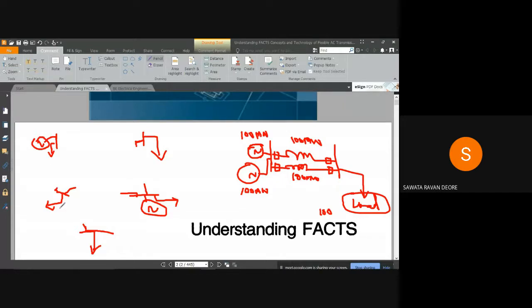So in this example, every city or district, let's say these are 5 districts of Maharashtra, has one generating station, and from that generating station the whole district distribution network along with a 132 kV level transmission network has been built. That is equivalently represented here as a single bus, where that 132 kV bus is connected to the main grid.